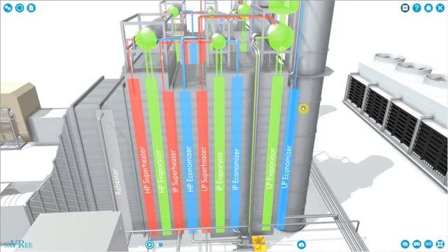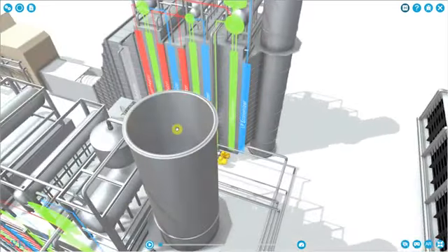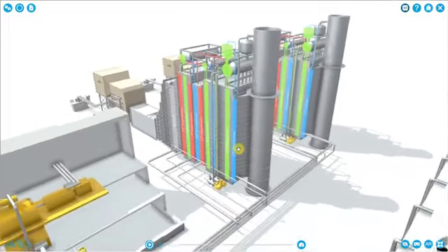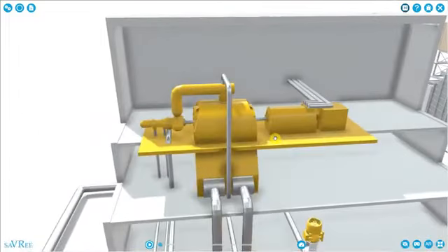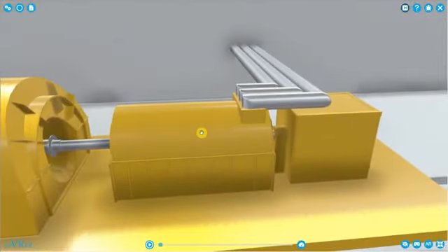At this point, the hot gases, the exhaust gases, can be discharged through this hole and to atmosphere. The steam from the heat recovery steam generator is sent to the steam turbine, and then the steam turbine rotor rotates and we generate electricity through our generator here.